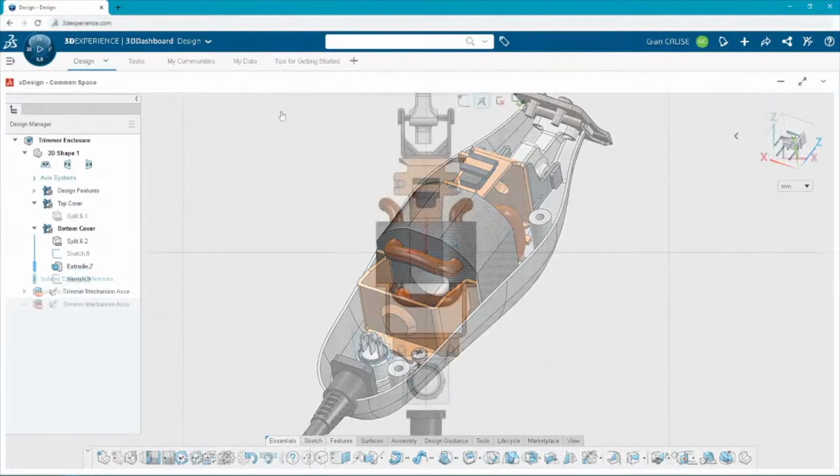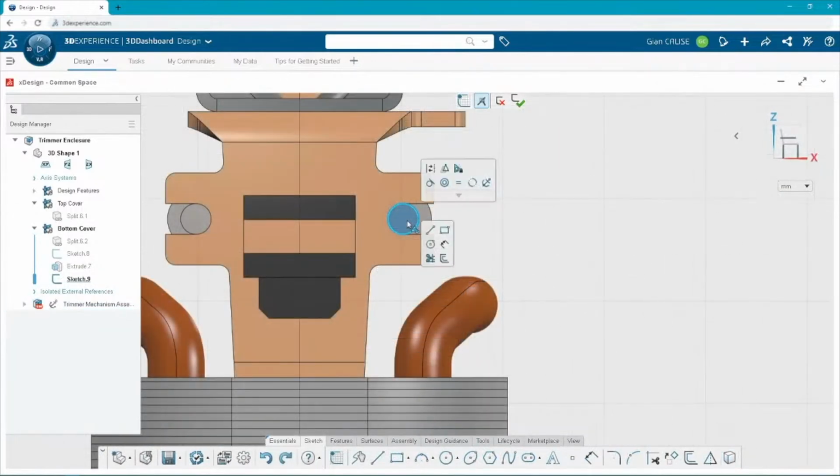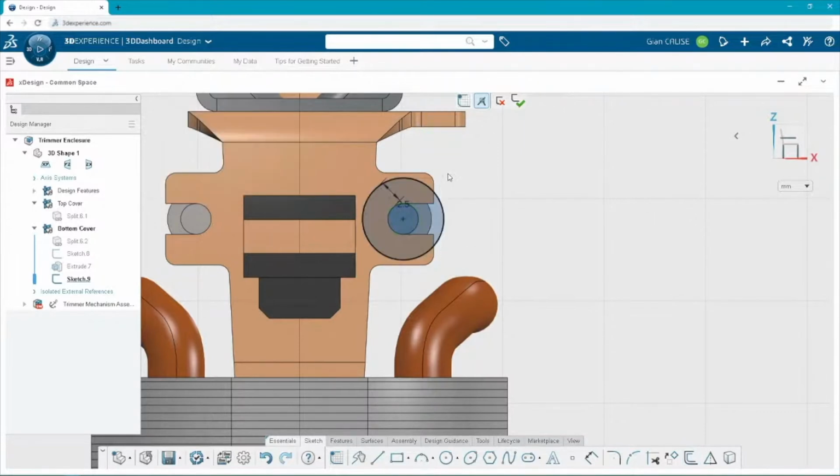And now let's move on to start including some of the rest, like the screws that John already put in there. I'm going to take those edges and convert them. I'm going to use those to my advantage so I don't have to do any sketching. And then here's the S key again. The S key is not just for SOLIDWORKS. It's for 3D Creator. It's for 3D Sculptor. It's really anything SOLIDWORKS can get its hands on. You could probably bet that the S key is going to be pretty darn helpful. So in this case, it's giving me a bunch of sketch shortcuts. So I'm going to use the offset. I could drag that manually, but I think I'll just do 2.5 millimeters. I'll just type that in.